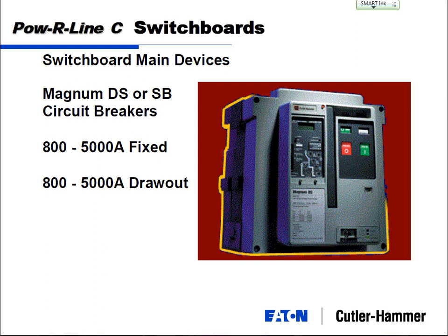One of the differences between a molded case and an insulated case for air power is this breaker here. When you look at it, you can see it's pretty big. It's all individual parts. You've got springs and washers and bolts and all this stuff on the inside. You can take this breaker, put it on the shelf, break it down, clean it up, sandblast some stuff, put it all back together, replace a part here and there that's needed, and get that breaker to last for years, 50 years, 60 years, what have you.